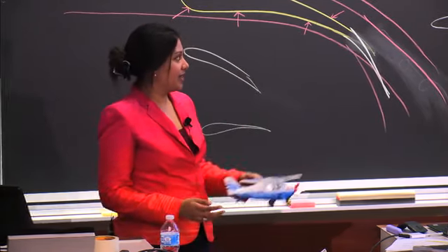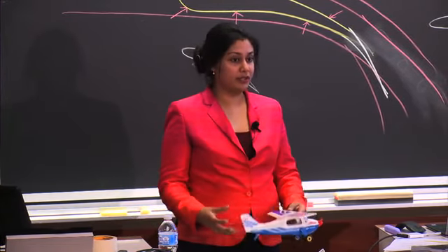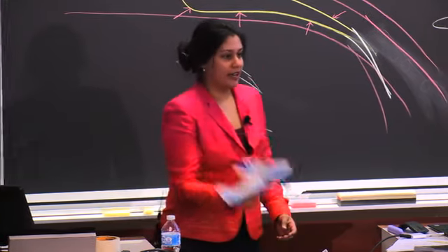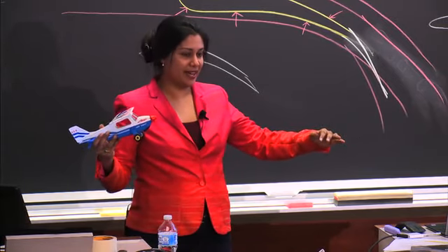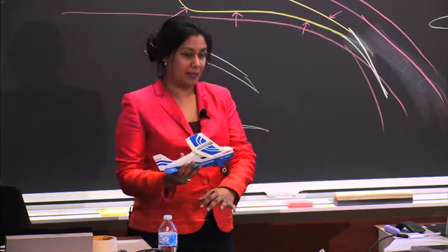The reason that you do that is basically that by increasing your lift, but also increasing the drag, drag affects how fast you're moving forward, right? And so you can actually have your airspeed be higher with the ground speed being lower.